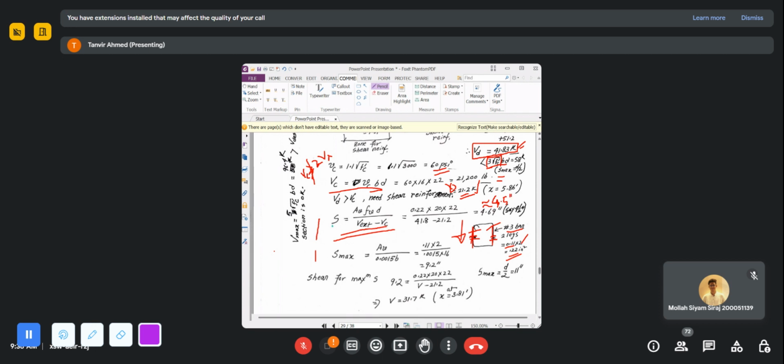For spacing we round down. We discussed this in the slab design, that when we calculate the spacing, we normally round it down. Okay, and for area we round it up. For area we normally round up, for spacing we round it down. So 4.69 came from our calculation, we will provide 4.5 inch.